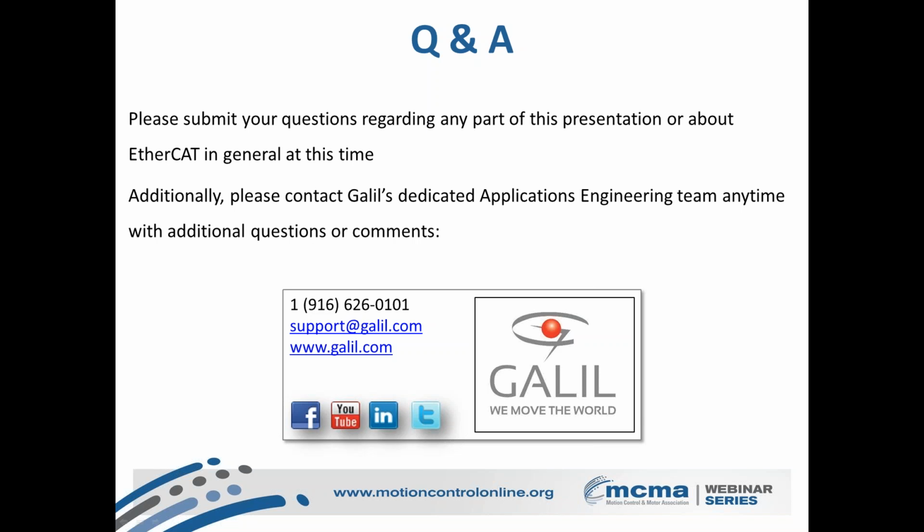Okay. Well, it's somewhat similar to the analog analogy. If you have any kind of servo drive that takes the plus or minus 10 volt servo command signal, then the actual amplifier or the motor size or the motor type that's being powered on the other side is completely invisible to the motion controller. And in the same way with EtherCAT, if you're in position mode, where the master is sending out that 32-bit position number, whatever drive is on the other side is going to look at that number and say, I need to move this many counts, whether that be counts or steps, whatever it is. The type of hardware is going to be transparent to the EtherCAT master.